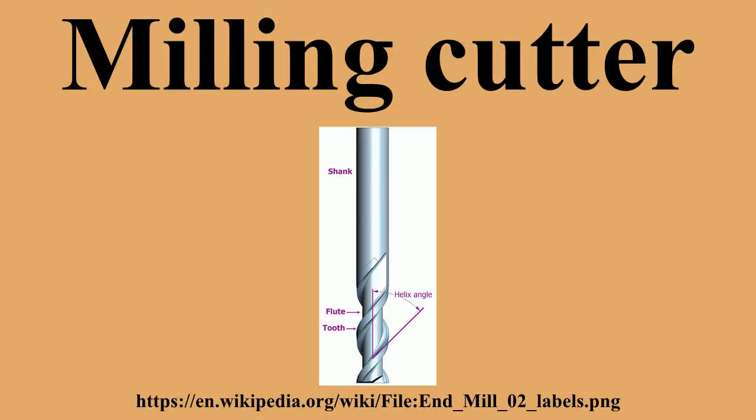Diameter. Larger tools can remove material faster than small ones, therefore the largest possible cutter that will fit in the job is usually chosen. When milling an internal contour, or concave external contours, the diameter is limited by the size of internal curves. The radius of the cutter must be less than or equal to the radius of the smallest arc. Flutes. More flutes allows a higher feed rate, because there is less material removed per flute, but because the core diameter increases, there is less room for swarf, so a balance must be chosen.